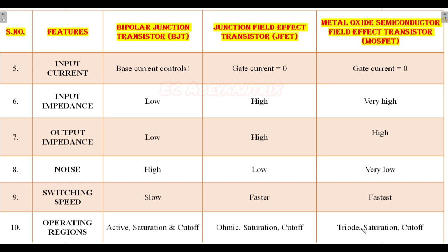You remember Shockley square law equation? We have learned that, it's a very important equation actually for exams. ID equal to IDSS into 1 minus VGS by VP the whole square. There VP means pinch off voltage, or VGS off also refers to pinch off voltage only. We remember that formula, right?